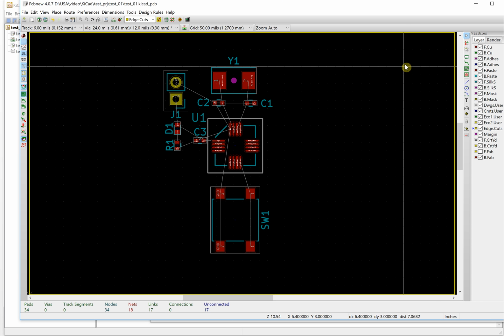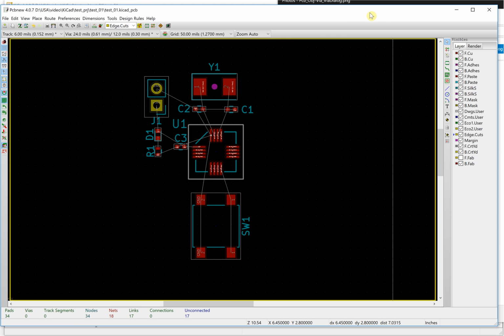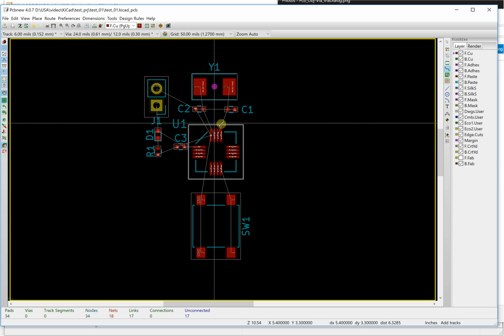Okay, so you route it. You do the PCB layout, and you will need to choose which layer you lay out the first things on. This is front layer, front copper layer, and this means the first layer. Okay, this is back copper layer, the bottom layer, top layer, bottom layer. You choose here, and then we choose this track, add the track. Okay, we check.